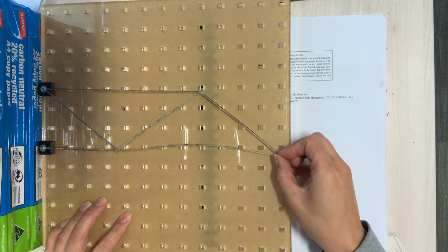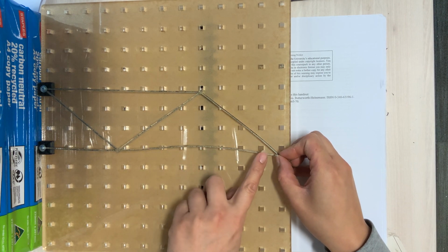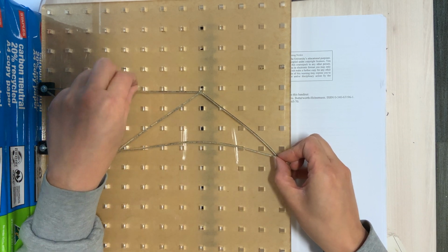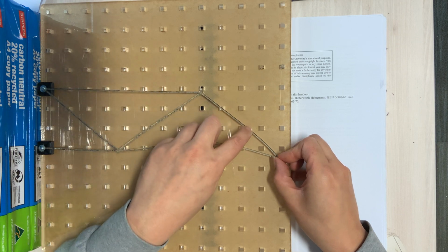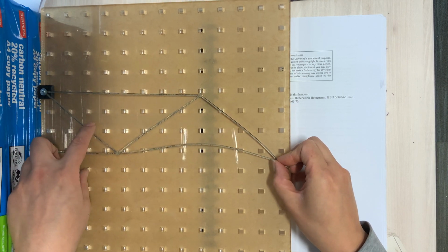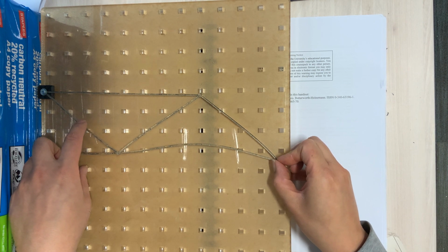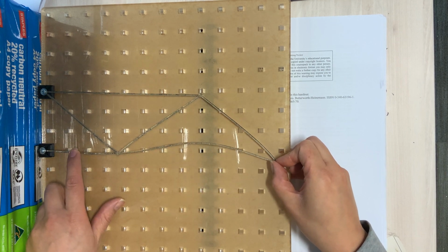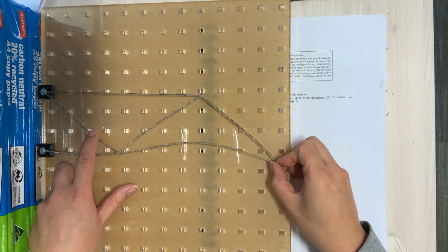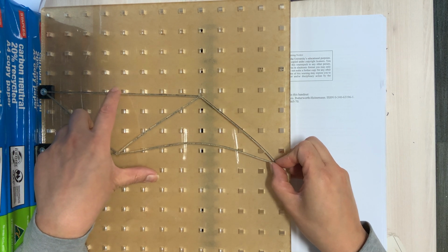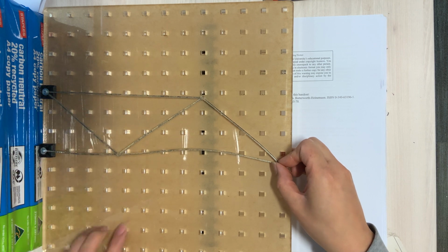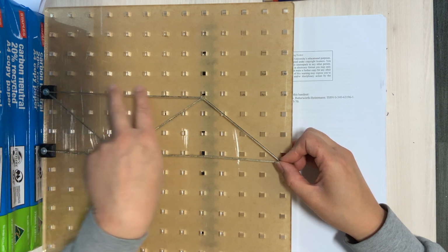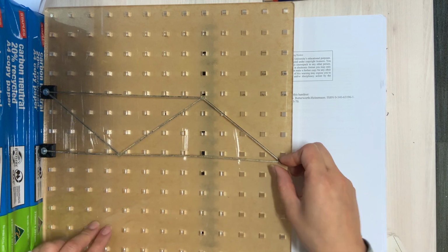Just pulling it down slightly indicates, because only the compression ones will want to buckle. So that one is clearly in compression, and you could probably feel the tension. So if you had one of these, you could probably feel which ones of these members are in tension. So that one is in tension, that one would be in tension. So you can actually feel it just by playing, just by playing with it, whether something's in tension or compression. Obviously if you're pulling it down, then if it was a beam, that would be the tension side and that would be the compression side anyway.